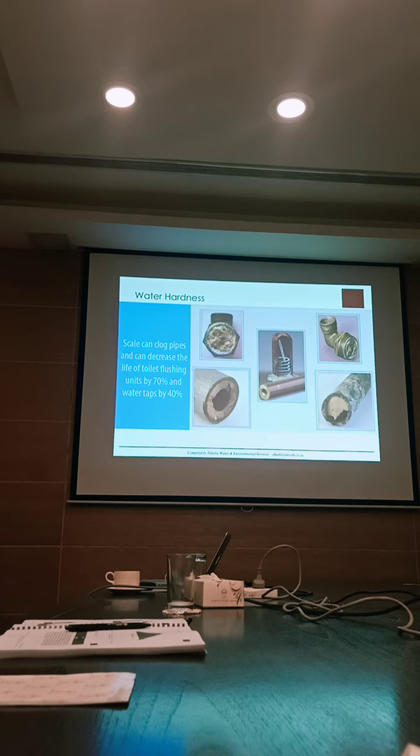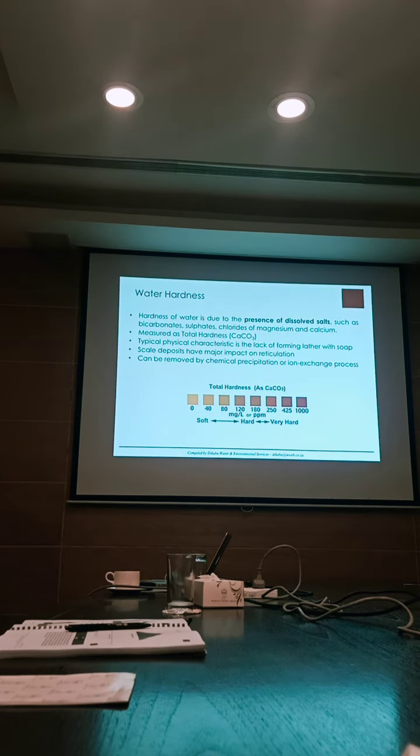So you can choose. But some people would just rather plan maintenance and replace pipes. But normally it's for the inlet water; you can see if we increase the temperature, there is always scale. That's why we always go for descaling. It's for the normal routine process. So you should measure your hardness. If your hardness is around 80, that's where you want it to be. If it's too soft, it's going to be corrosive.